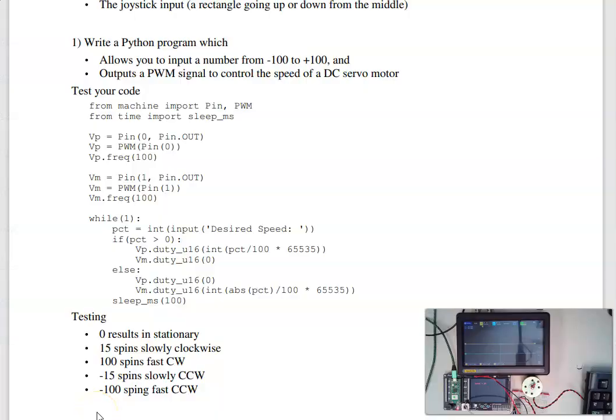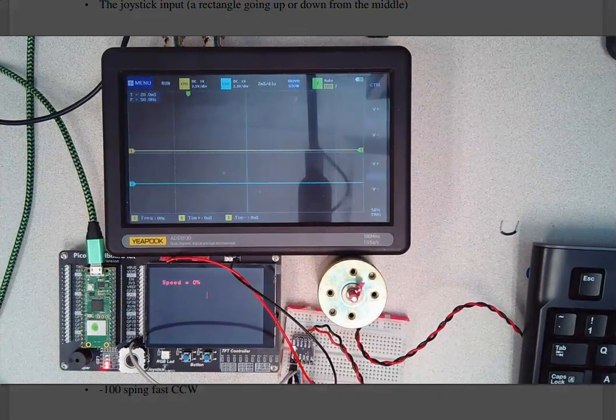Well, the first problem is to come up with a way to drive a motor forward and backwards using PWM. So for the connections to the motor, I have an H-bridge. See down here, the Pico outputs voltages to an H-bridge, channel A and B, that drives the motor's output. When I apply 3.3 volts to A, the motor spins forward, 3.3 volts to B, the motor spins backwards. Now I do a PWM output to control that.